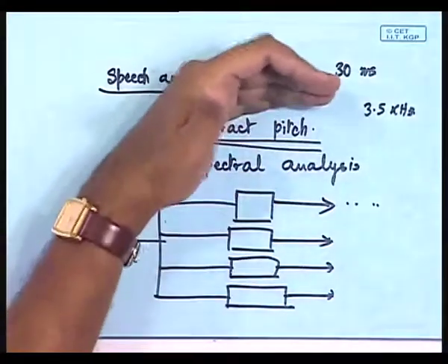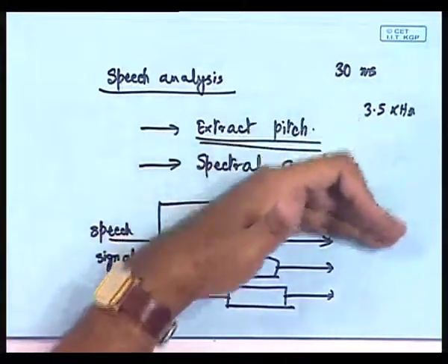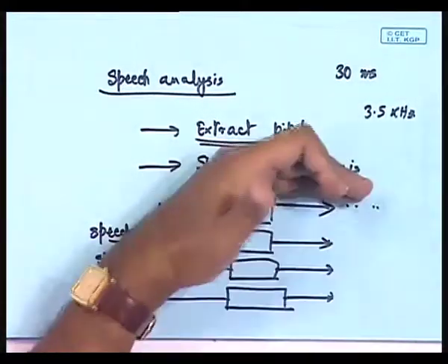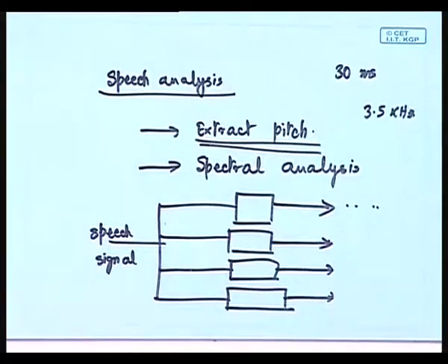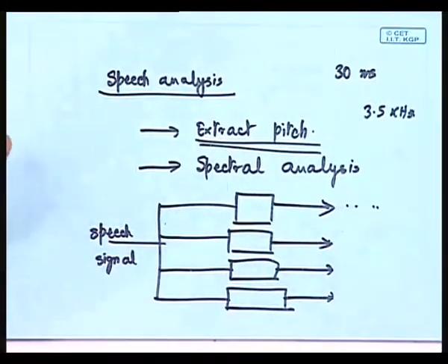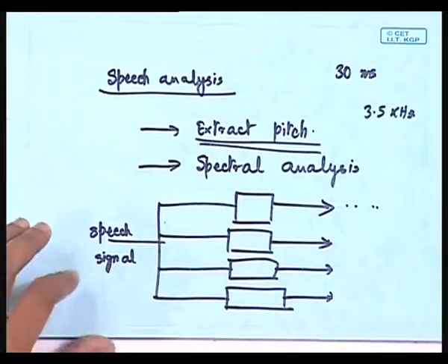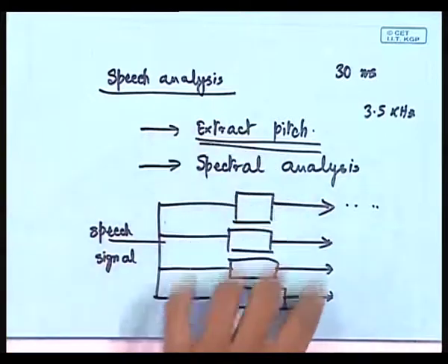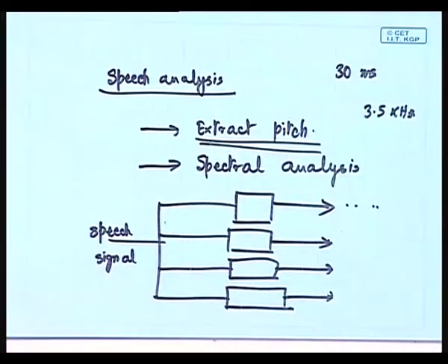And not only that, there is also one more point which you should keep in mind: by having a speech analysis and only giving the pitch information and the individual band energies, and also of course you have to give another flag, whether it is voiced speech or unvoiced speech. If it is unvoiced speech, then one has to switch on a noise generator in order to do the speech synthesis. So, this sort of information representation also will be more compact.